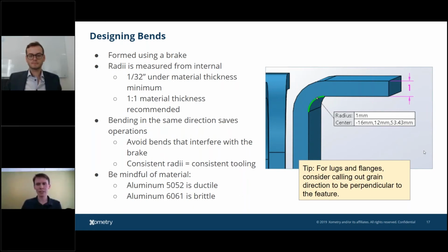So here's my quick animation. The other thing, though, is when you're bending, note that I need to have a design that bridges that entire V-block section, because if not, when I put a press down, these strong hydraulic driven presses could actually pull the operator and pull your part forward and not actually create those features. So when we talk about minimum flange length,